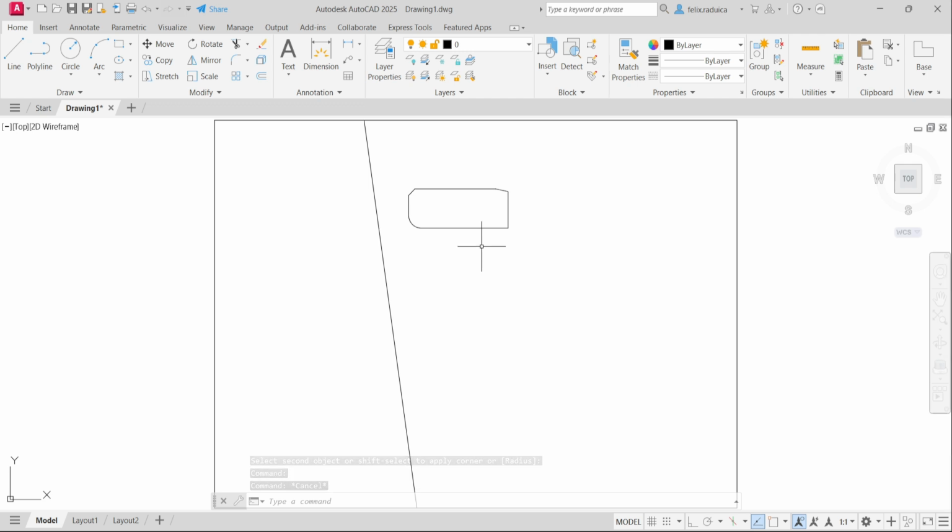Sometimes I want a closed loop like this one to be one object, like you see here, but other times I may need only a few elements, or I need to delete something from this, but not all of it. So in order to break this into elementary objects, I can use the explode command, and I can select what I want to explode and tap enter.